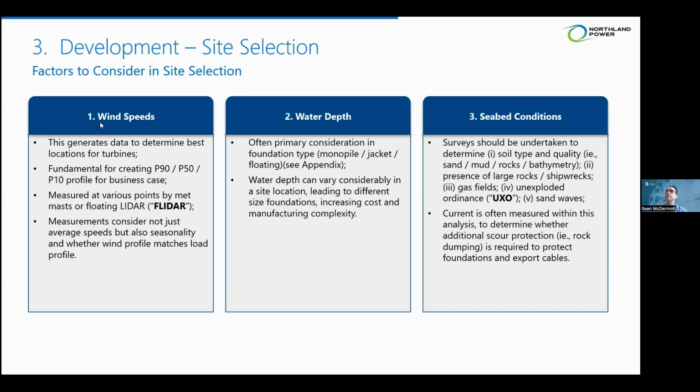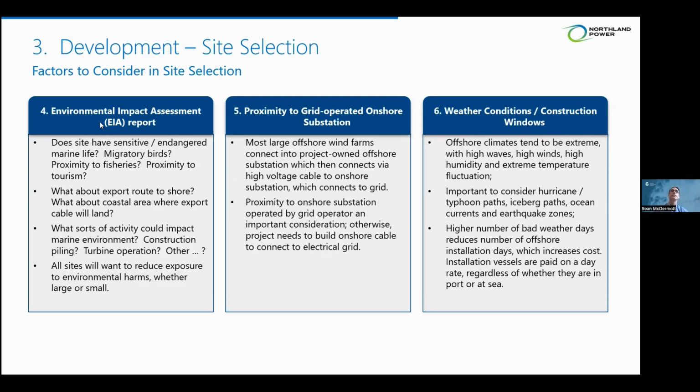In Taiwan, we needed to spend a lot of time thinking about sound waves, which had to do with the speed of the current and where the water was moving. And then you do have things like mud types, sand types. You want to be able to dig, you want to be able to put your foundation into something that will hold the foundation, because the foundation is heavy and the turbine is heavy. And it's important to have a good sense of what it is you're going to be putting your turbine and foundation into before you proceed. So that's an important consideration.